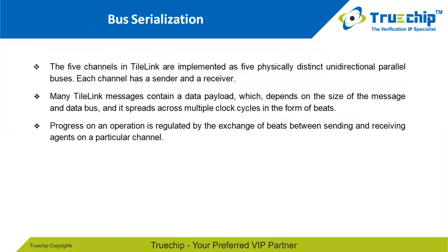Now, all the channels are implemented as unidirectional parallel buses. Each has a sender and a receiver. Many TileLink messages contain a data payload depending on the size of the message and the bus, and it needs to be spread out across multiple clocks as beats. Any operation is regulated by the exchange of beats between the agents on a particular channel.